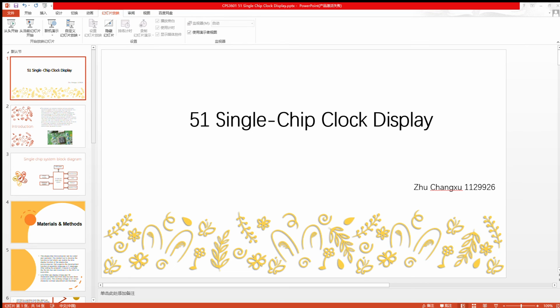For the key scanning flowchart, we can see that due to the device characteristics of the key, there will be jitter at the moment of pressing or releasing the key in actual use. We must eliminate the jitter before normal use.